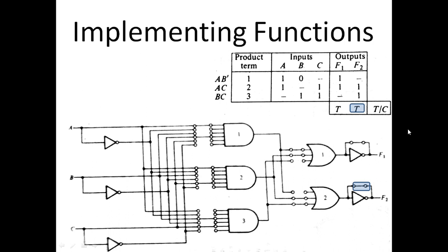After representing the Boolean functions in the sum of min terms form, remove the redundant product terms. If there is a product term in one function and also it is there in all other functions, keep it just once and remove all other occurrences of that product term. So the second step is to remove the redundant product terms. So you would get a set of product terms. The third step is to create a PLA program table, just like this.